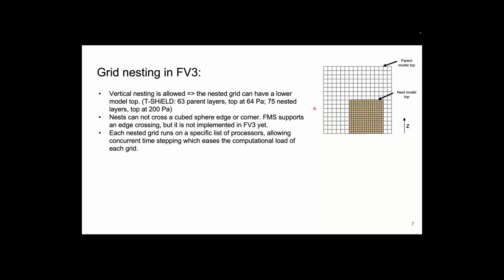At the beginning of a simulation, we distribute the processors over the different grids, so the user can specify how many processors are needed on each grid. That makes the algorithm very computationally efficient and allows for load balancing on each grid. Otherwise, things like telescopic nesting, if you do a serial computation, will not be very efficient.